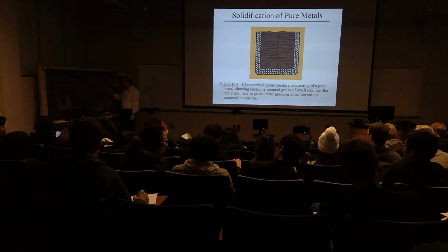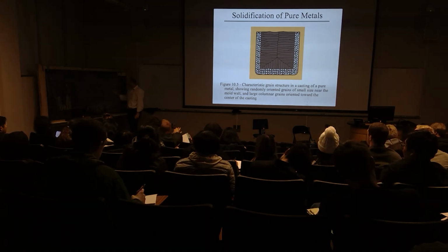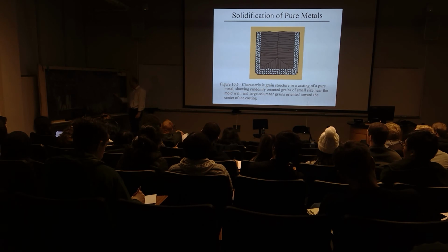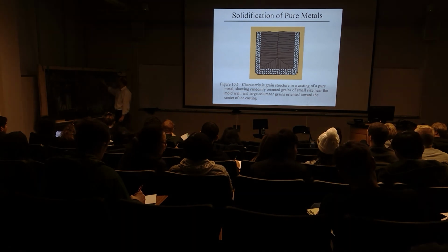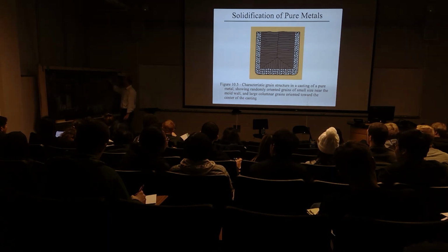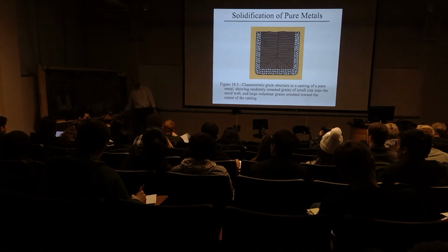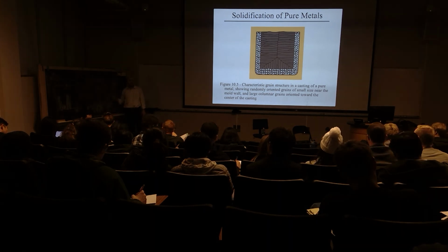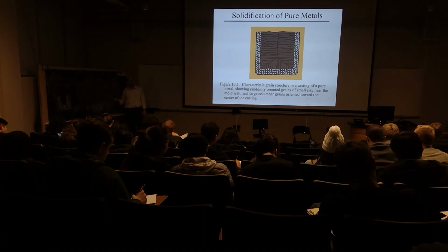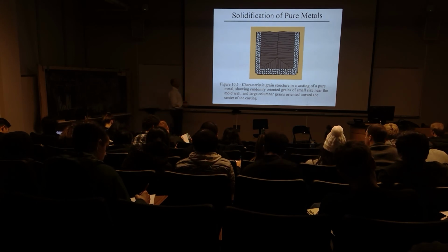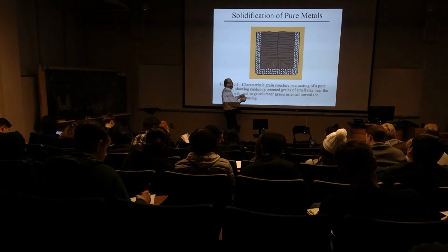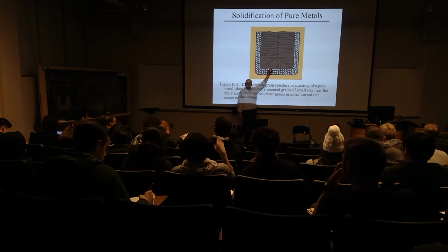Let's say sigma naught plus K over the square root of D. What does that look like? Yeah, this is definitely something that you have used and you know it applies here. This is the Hall-Petch relation. So a casting will always have its strongest portion on the skin, and the interior will be the weakest because the grains are larger, because heat conduction was less rapid.